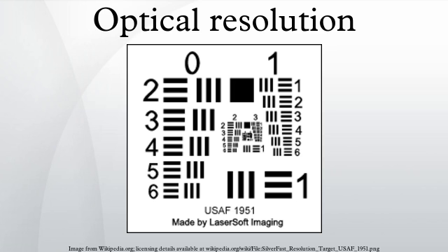Pyroelectric detectors respond to changes in temperature. Therefore, a static scene will not be detected, so they require choppers. They also have a decay time, so the pyroelectric system temporal response will be a bandpass, while the other detectors discussed will be a low pass.